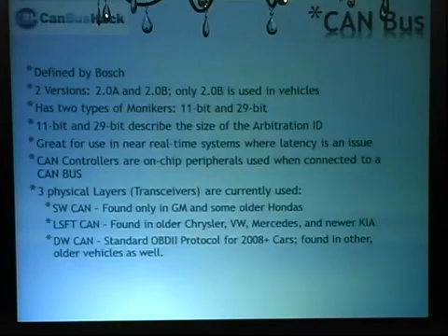It's really good for real-time systems, very low latency. You send the message out, and most vehicles are running about 500 kilobits per second, really super fast, blazing, 500 whole kilobits per second. If you think about an 8-byte frame that goes out at 500 kilobits per second, it only takes about 280 microseconds for it to be on the bus, and then it's gone. Then there's the next one that has time. So if you think about all the information that you pack into 280 microseconds, it's really fast, and then all these other controllers can share it, so it's really close to real time.